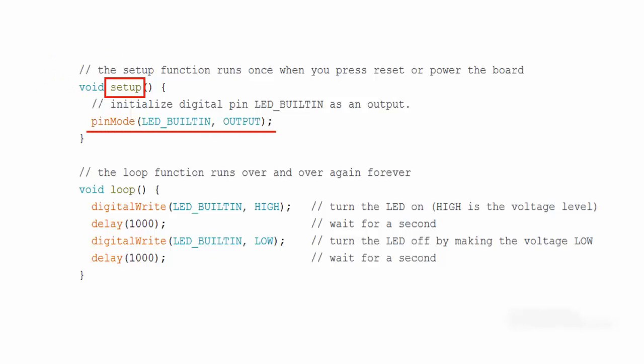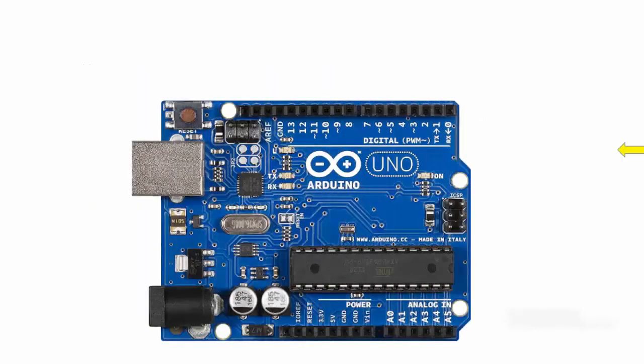Many boards have a built-in LED to test being programmed, and in most Arduino boards, this LED is also connected with the digital input and output pins. In the case of Arduino Uno, we have a built-in LED and it is connected to digital pin 13. Defining the built-in LED in output mode means that digital input output pin number 13 is configured as an output pin, which will output 5 volts at regular intervals in parallel to the built-in LED. We can connect an external LED with pin 13 in order to make it blink.